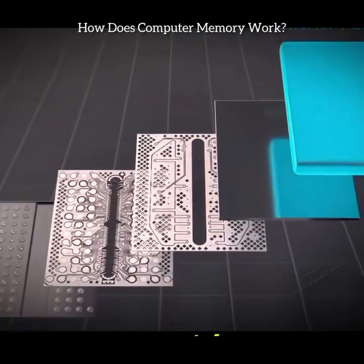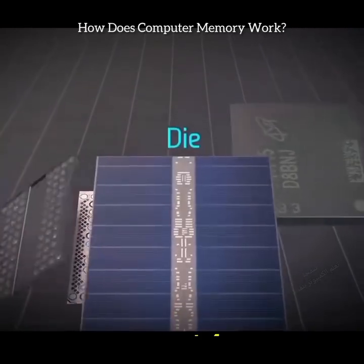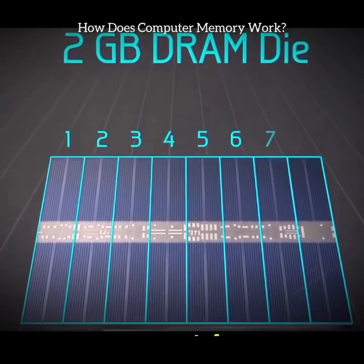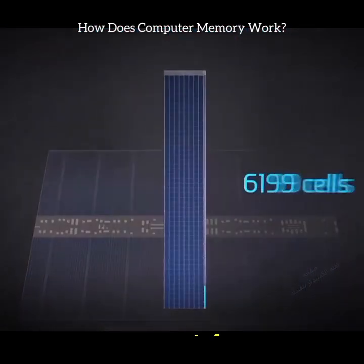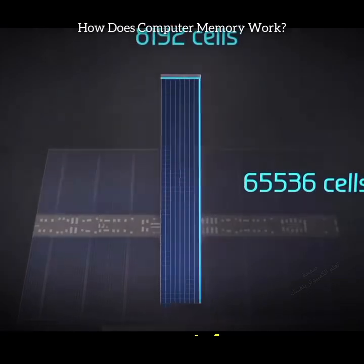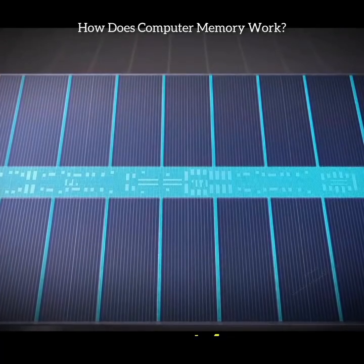Inside the exterior packaging, we find an interconnection matrix that connects the ball grid array at the bottom with a die which is the main part of this microchip. This 2 GB DRAM die is organized into 8 bank groups, composed of 4 banks each, totaling 32 banks. Within each bank is a massive array, 65,536 memory cells tall by 8,192 cells across, essentially rows and columns in a grid, with tens of thousands of wires and supporting circuitry running outside each bank.